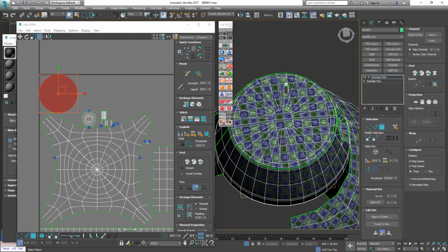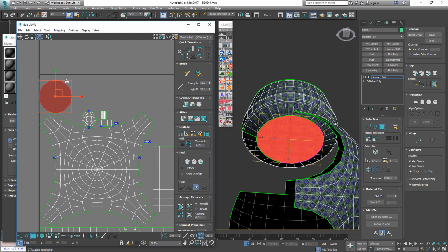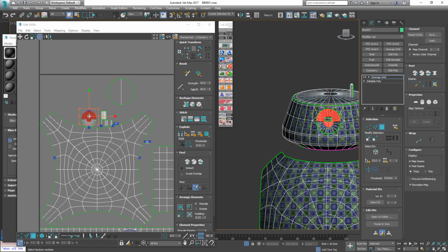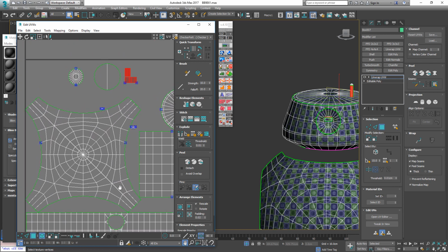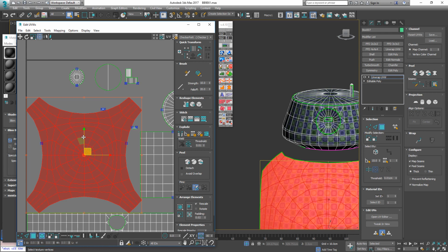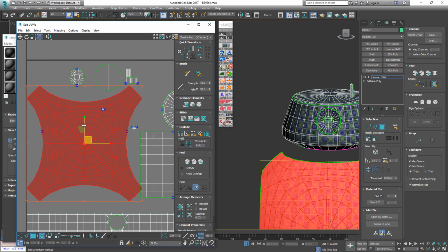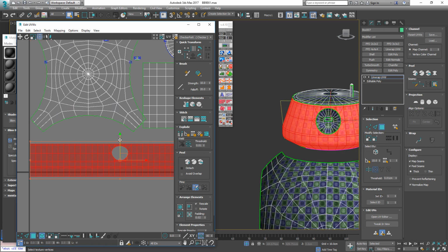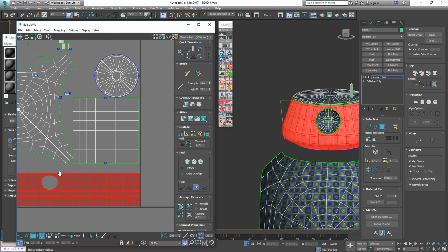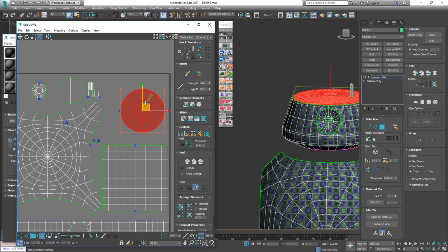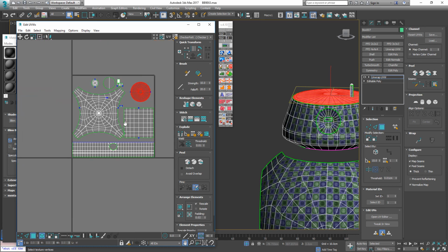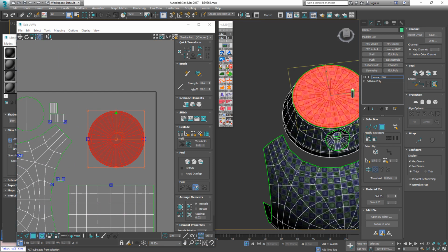Let's select that piece here. It's that polygon element and we will barely ever see it, so I'm just gonna scale it down a bit. Let's go over here to the element mode down there at the bottom left. Makes it easier to select things. And let's rearrange it a bit here from what our auto packing was doing earlier. That won't be the most efficient unwrap ever because we have such few elements here to work with. But we're just gonna try to make it as efficient as possible here within our texture space so that we don't lose too much of it.